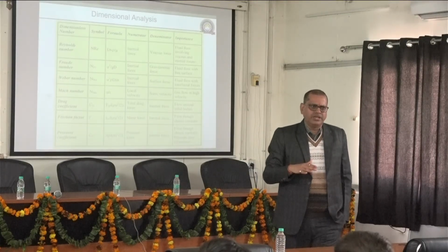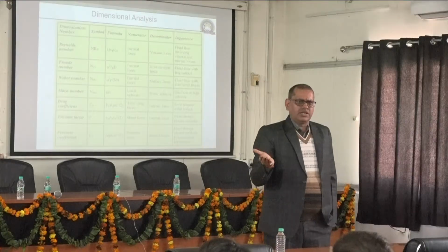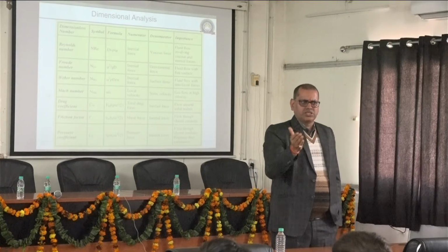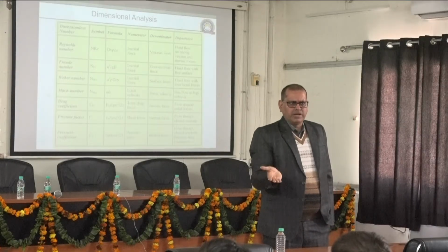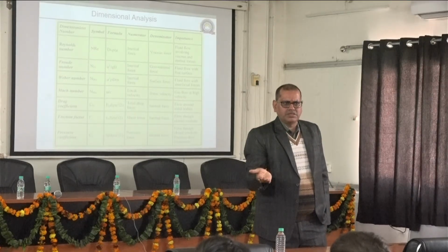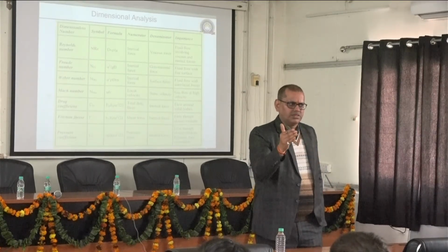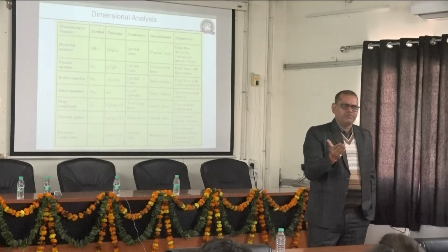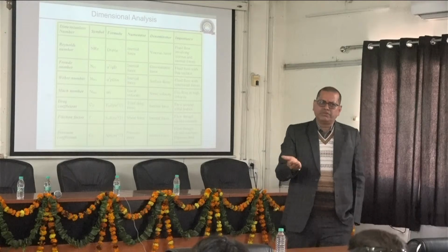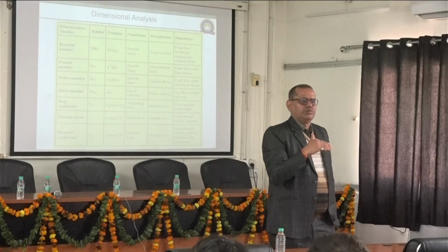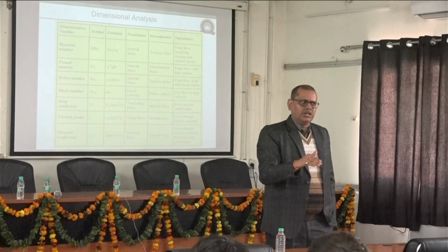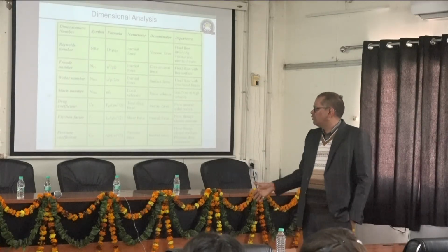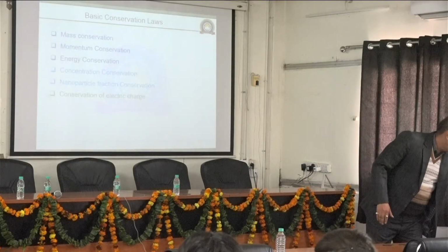Another advantage is that after dimensional analysis your governing equation will also become simpler, because you can take some assumptions and approximations. You can transform your non-linear problem to a linear problem, or sometimes your non-linear problem can be handled through some technique. So that is the advantage.